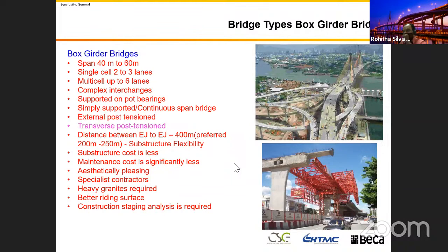I'm not going to talk much about that one. You saw that bridge. The box girder you can use as simply supported. The special thing with this one is that we put in the transverse post tension. Of course, you know that you can't design a reinforced concrete element with 6 meters in span, having two trucks on that side with the barrier and weight. Because of that, you need transverse post tension in this kind of structure.